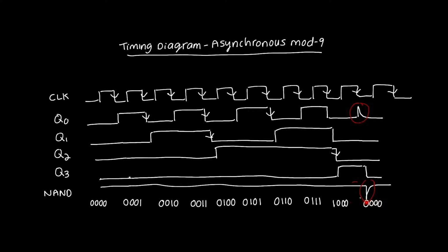And when that happens, because the output of the NAND gate is connected to the asynchronous reset of all the flip-flops, they are reset back to 0.